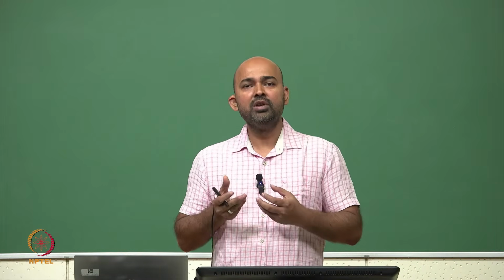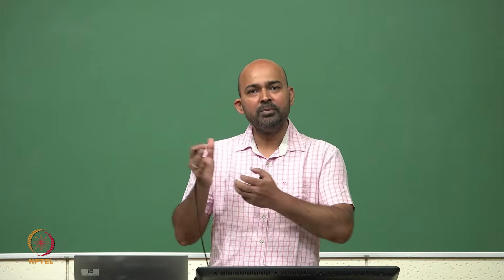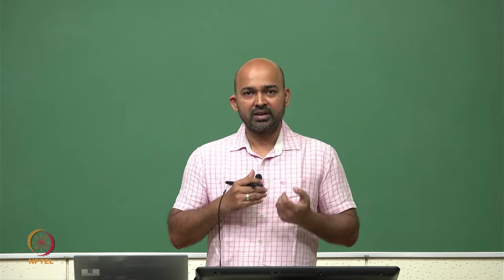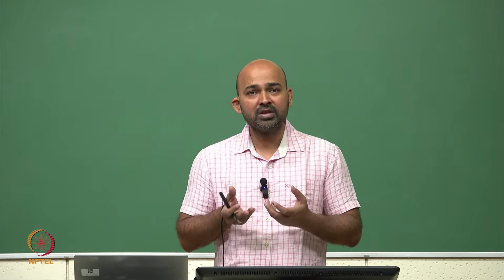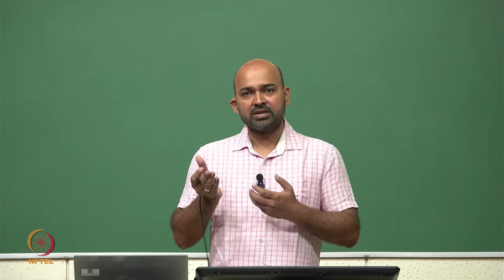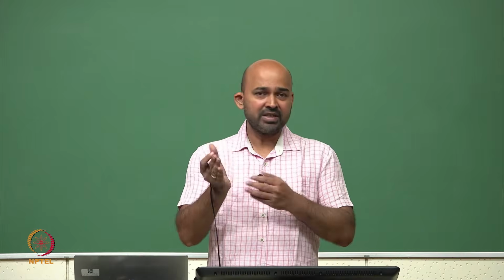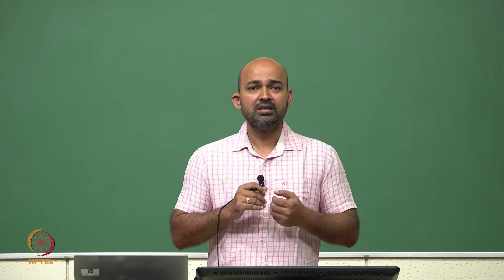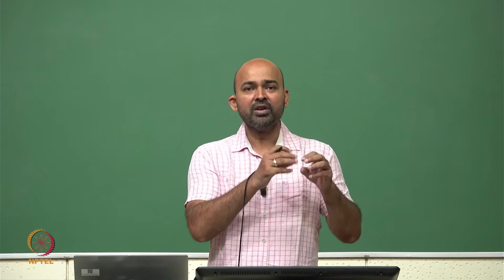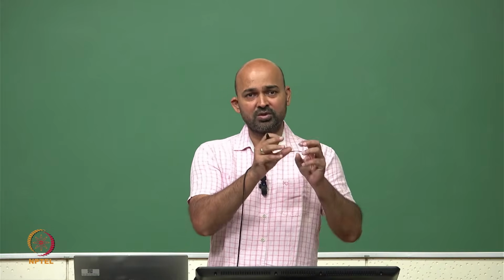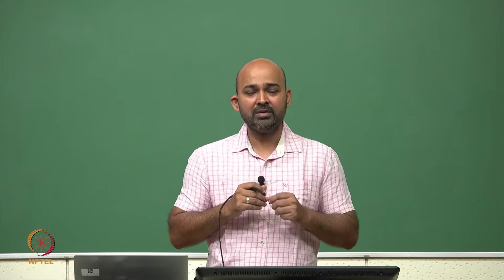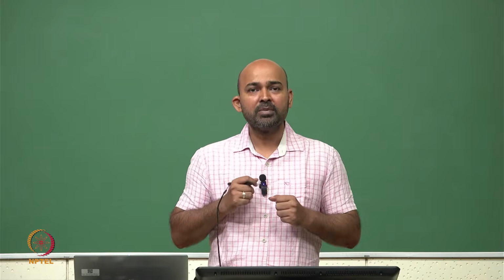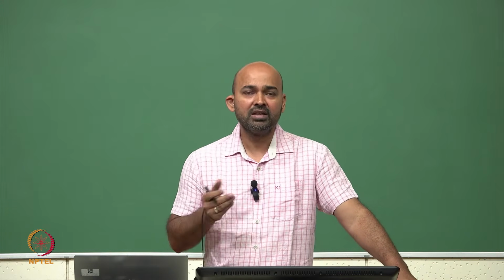After that, often we need to simulate the circuit for a complete sweep in some parameters. For example, we have an electronic circuit, and we want to see the behavior of the circuit with respect to temperature. Temperature is a parameter which can vary within a certain range. The components we choose, for example the voltage source or the resistors, inductors, even active elements, are all dependent on temperature and their characteristics change with temperature.